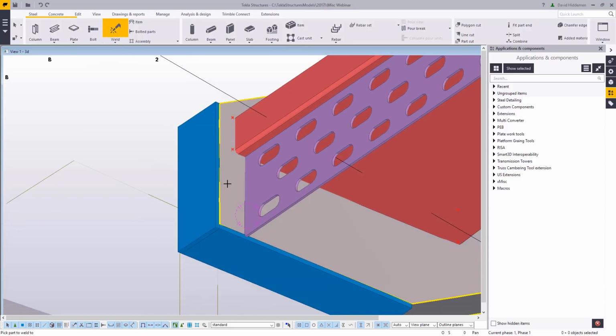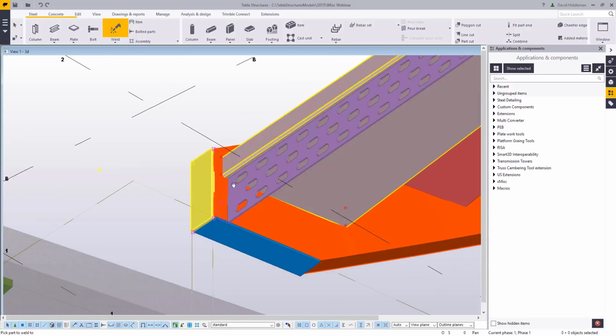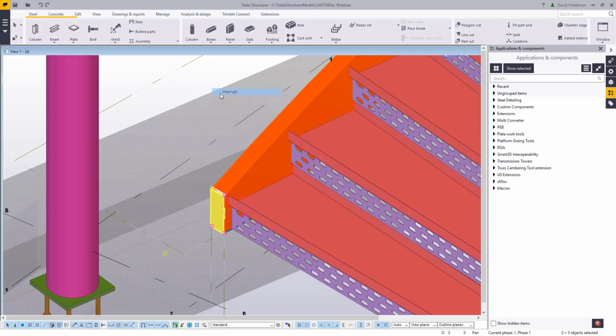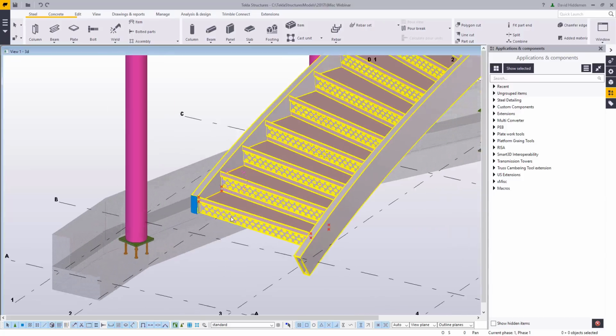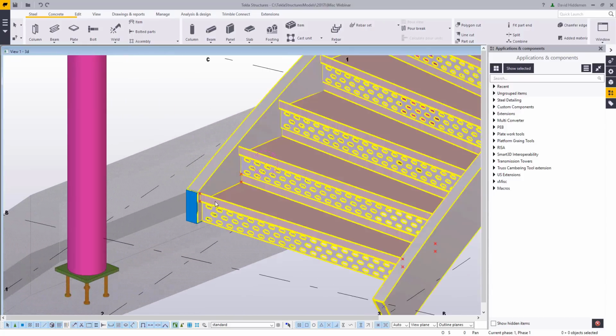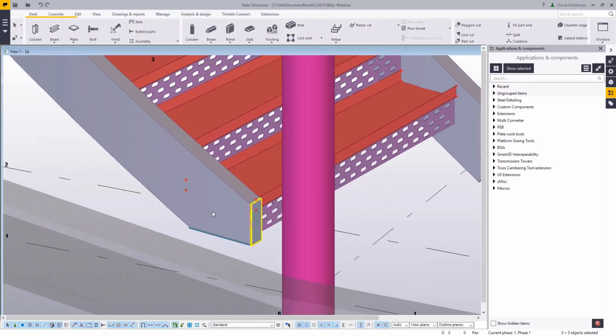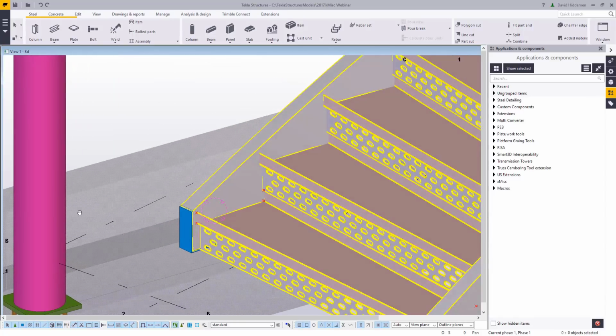Okay. Last thing you want to do when you're manually modeling like this is make sure that everything is welded together. Again, you want to mimic what you're doing in the shop, and I could do this for the other side and the top, but you get the general idea of how you can create these ends.